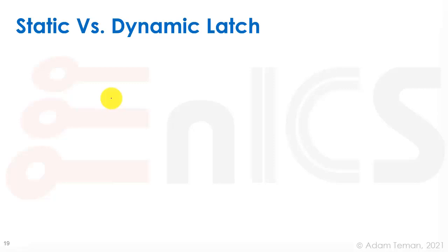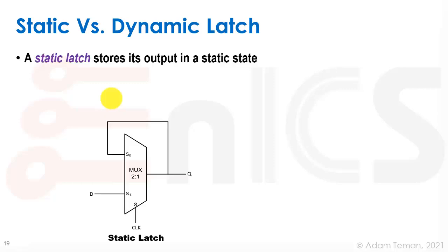So how do we actually make these latches? Well, there are two, I guess, basically types of latches, a static and a dynamic latch. A static latch, and this is going to be the type that is most commonly found, just like we use static CMOS type of logic. We like static things that replenish their data at the output, even if there are all kinds of noise and leakages. So static latches are very commonly used. And a high-level schematic of a static latch is just a multiplexer.